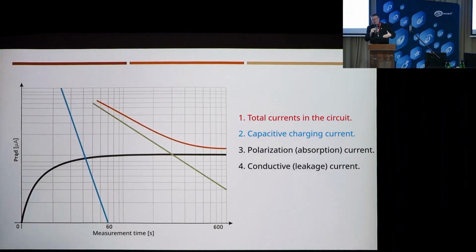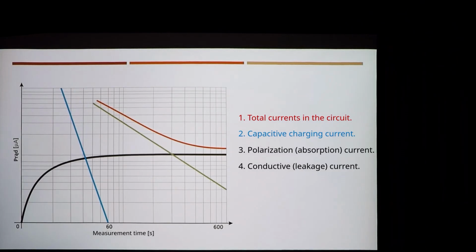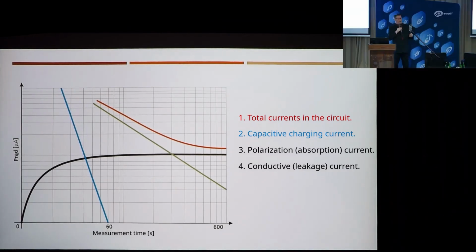And here's the phenomenon that at the beginning, since the current is large, the insulation resistance indicated by the meter will be low. As the value of that current gradually drops, the resistance indicated by the meter will rise. Here we can immediately answer the unasked question, when should you read the result? Well, when those phenomena die out, or when they no longer have any metrological significance. Because if, let's say, we exceed the meter's measuring range here, then we can wait another hour, even an hour and a half, but nothing will change there. It'll be the same.